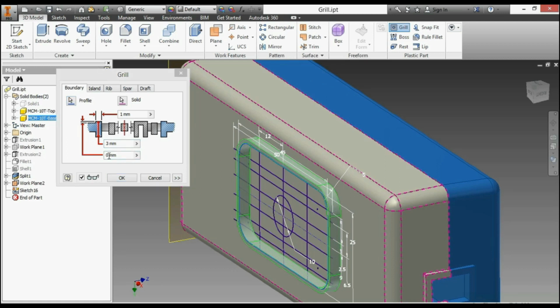However, you'll notice that it currently shows 0 being raised above. So if I adjust this to be, let's say 0.5, it's going to adjust the grill to be 0.5 millimeters above. How about 0.75? So we have a little bit above and a little bit below. If we do the math on this, we have 0.75, then the 1.5 thickness, and then another 0.75 millimeters on the bottom side. We also have our thickness value here as well for the thickness of this boundary shape.